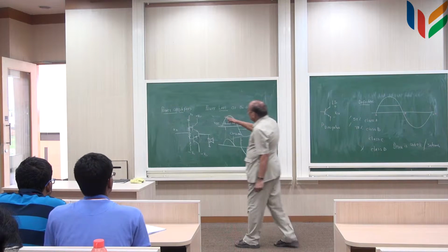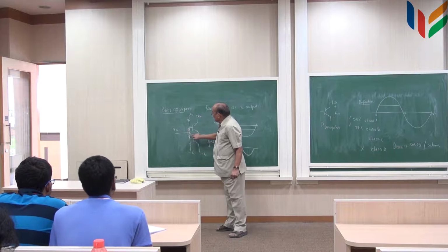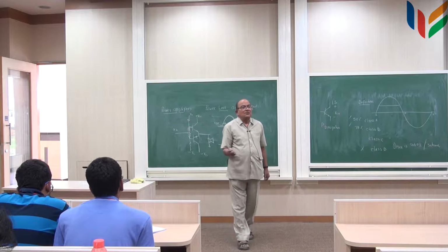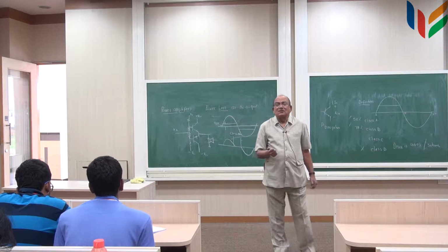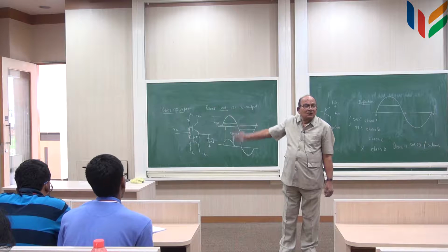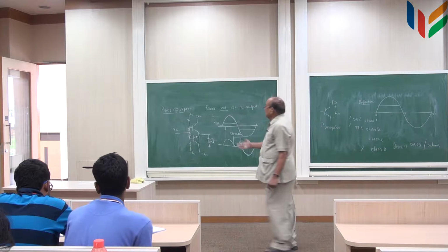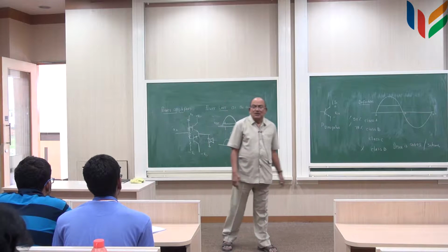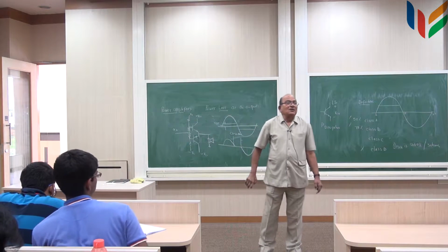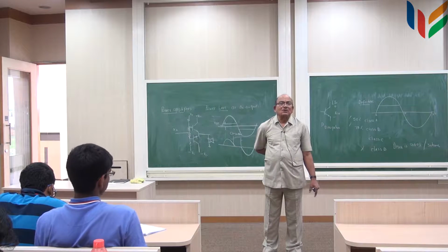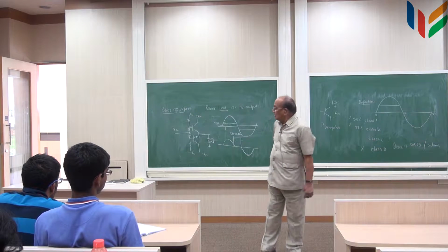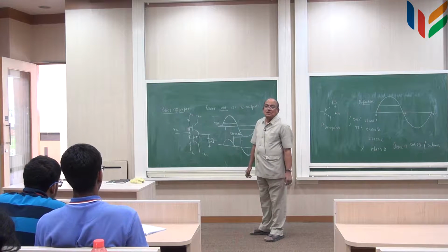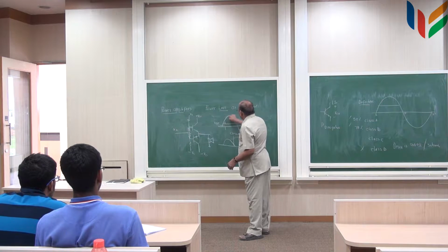This current through this is basically to make these diodes conducting, and the amount of current may be in terms of a milliampere or something like that, so good enough. So, the current that goes through that is a milliampere multiplied by VCC, and the power is extremely small. So, this pre-biasing takes care of the distortion due to this crossover. Now, the output will be a full sine wave output.